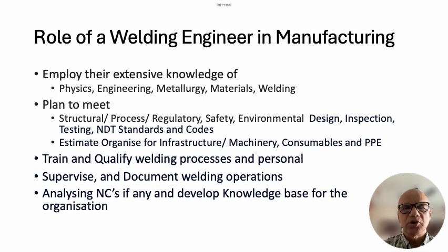So accordingly the joints, the trusses, the overlap, joining of materials is being decided. The process can be a carbon steel with stainless steel overlay to get corrosion resistance. It can be alloy steel with suitable heat treatment to achieve higher hardness or strength. Then there are regulatory, safety, environmental requirements.